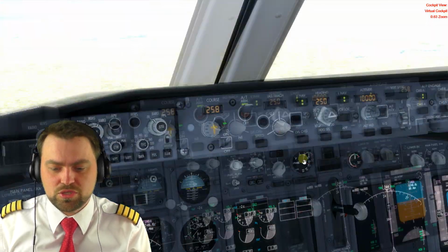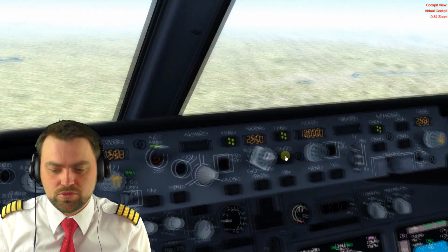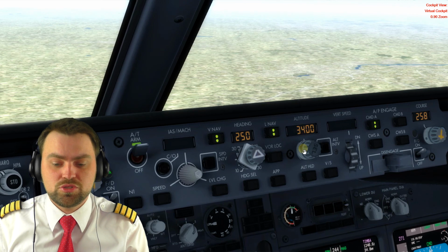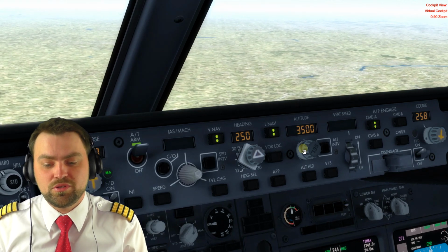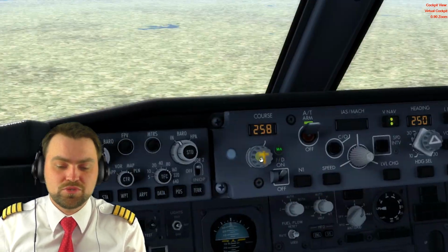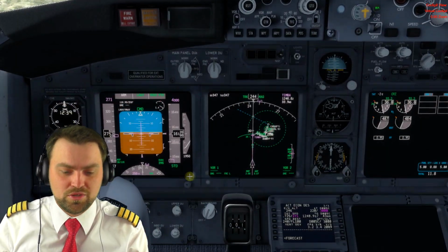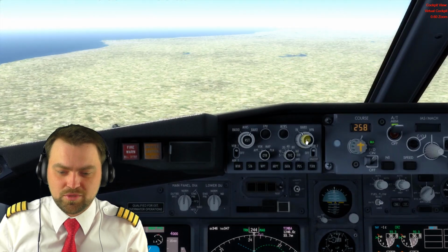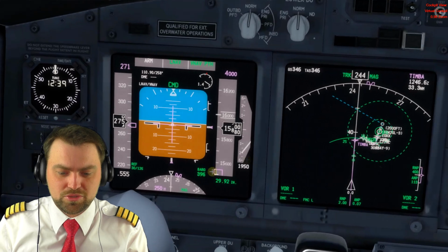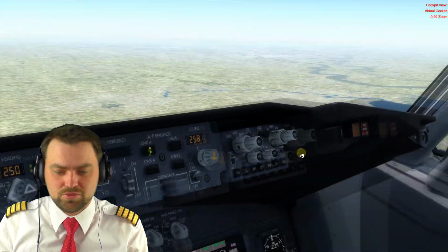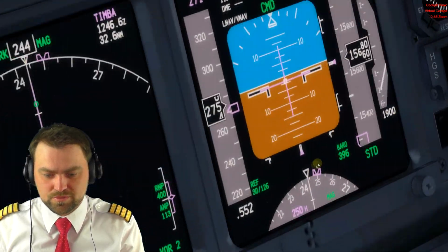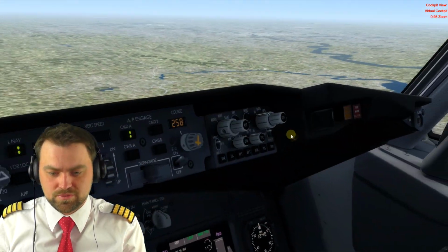So soon we're going to reach plateau 100, and now ATC says descend to 4,000 feet, QNH 2992. Well, actually in London you have QNH in hectopascals, which is 1013, but here we have a United States type of airplane, so I'll just press 2992 for captain and 2992 for first officer. I don't know, it's standard, still standard.